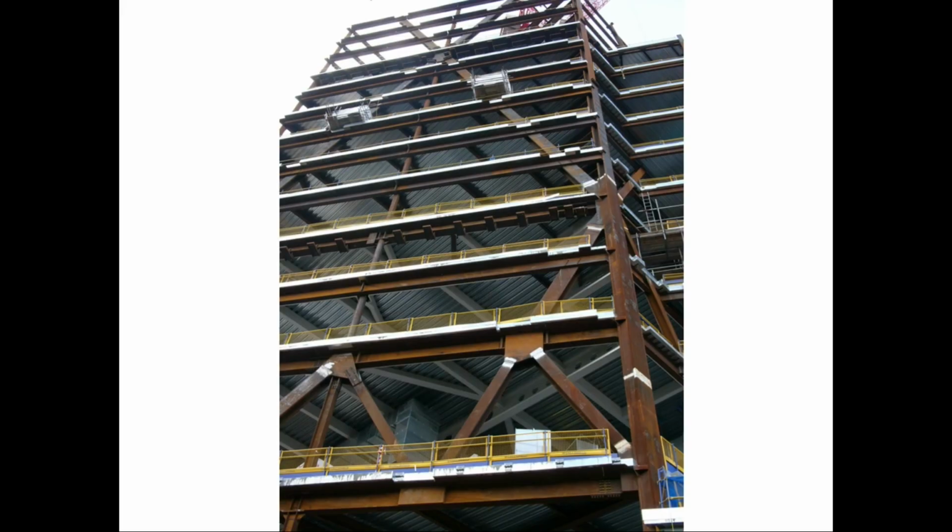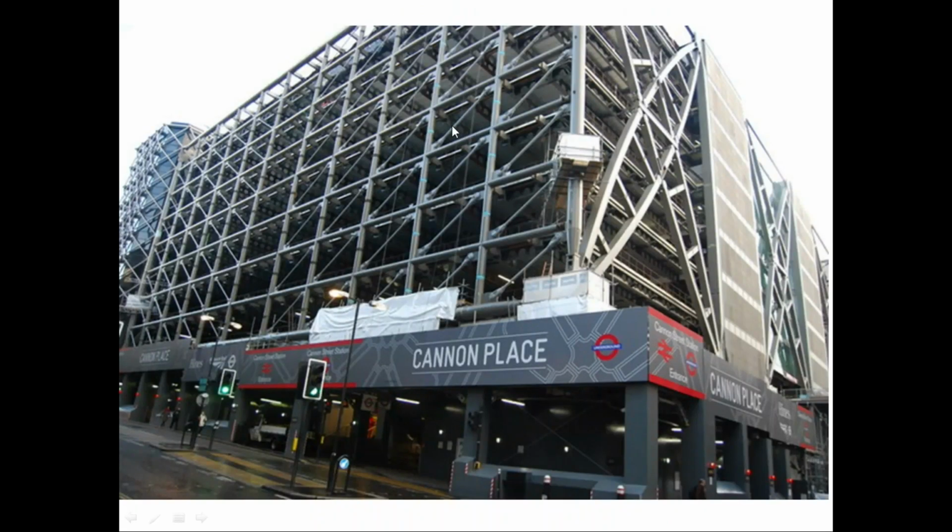So here are some examples of what we were just talking about. Here's a simple beam and column building, I'd say fairly simple. Instead of there being, say, constant triangles on every floor, as you can see, there's some major triangulation going on throughout the entire structure. These elements are bracing the structure for lateral loads, and you can see they're happening in more than one direction. They're happening on each face, if you like, of the building.